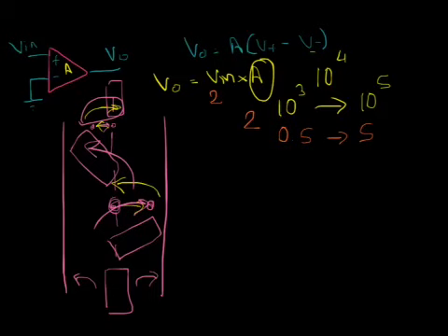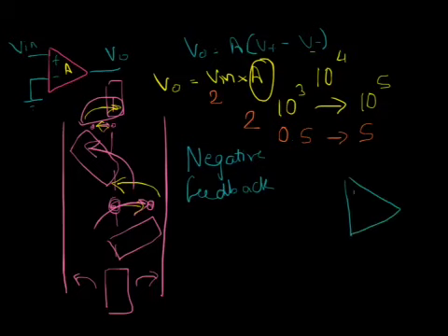That's exactly what we do in an op-amp, and we call that negative feedback. It's called negative because we move in the direction opposite to the error. So let's see how this actually happens in a circuit. So we have an op-amp. This is the Vout. So what we are trying to do is, if our Vout is supposed to be some ideal value, because of some disturbance the Vout increases.